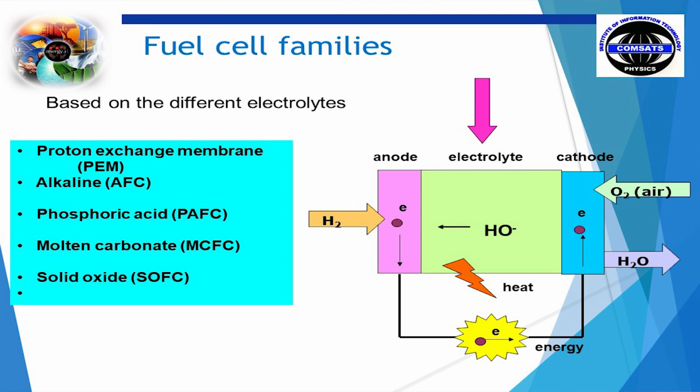As I mentioned, among the many challenges, ohmic losses are the main challenge regarding the materials when you lower the operating temperature. Also, there is the anode, electrolyte, and cathode, and there are some compatibility issues with some high temperature materials. If the different components have different thermal expansion coefficients, when you combine them into one device, it can be a problem, because the device can crack. So there are a lot of challenges with three components.